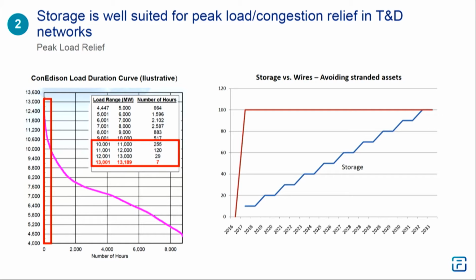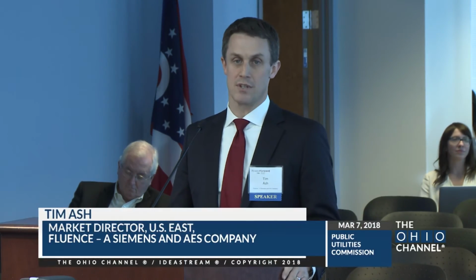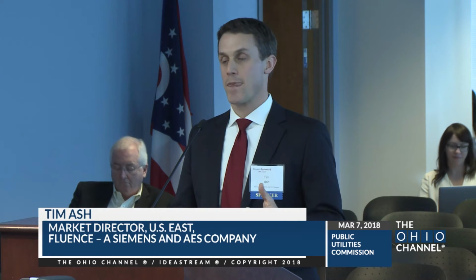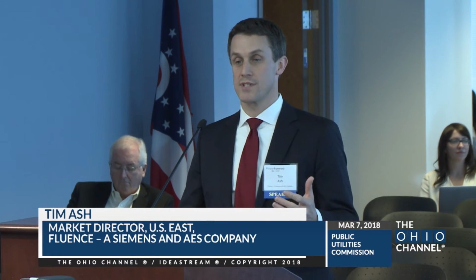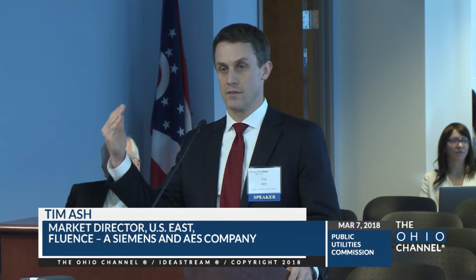The way we normally address that issue, though, is we've got load growing, starting to run up against the thermal limits of that substation or transmission line. We build a new substation, new transmission line. In some cases, it'll be very, very expensive just to meet those few hours per year. Instead, in some cases it makes more sense, it's lower cost, to deploy energy storage in the load pocket, support load during those peak hours, eliminate that thermal load on the grid, and now your existing infrastructure works. So again, it's lower cost.